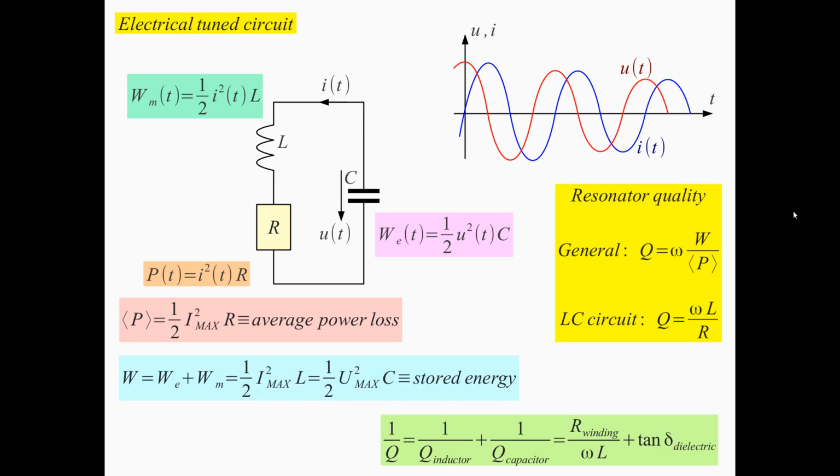So what are the components of an analog filter? We need reactive components like inductors and capacitors. And with one inductor and one capacitor, I can make a resonant circuit, an electrically tuned circuit to a particular frequency. And this circuit stores energy in the form of oscillation. So this is an oscillation circuit. Unfortunately, this circuit has losses.